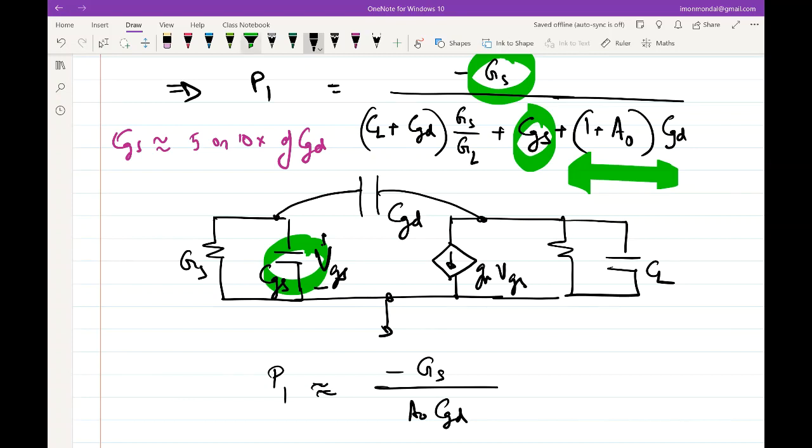And the first term that is sitting here in the denominator actually has an explanation. The argument is that since our amplifier is not a perfect voltage source, it's a voltage controlled current source, we don't expect a perfect Miller amplifier. Had our amplifier been a perfect voltage source, then this first term wouldn't have been there. I would have only had the Miller term and the CGS.